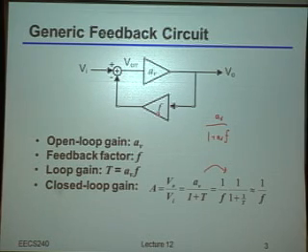Whereas to get gain, typically that means I need an active circuit that depends upon some gms and Rs, or gms matching some other load resistors, and so on and so forth. So this is really the reason that, if you want to set a gain precisely, doing it through a feedback like this is usually the best way to do it.